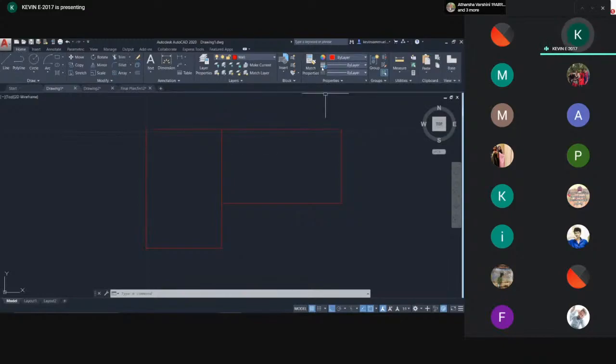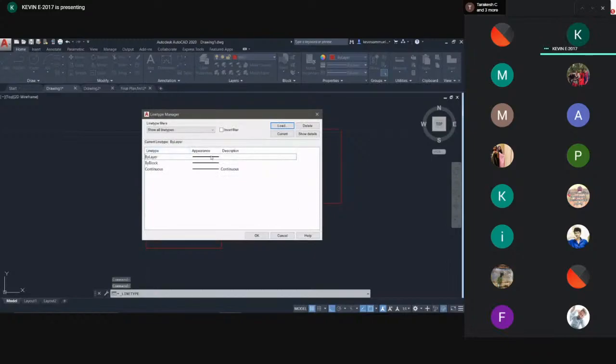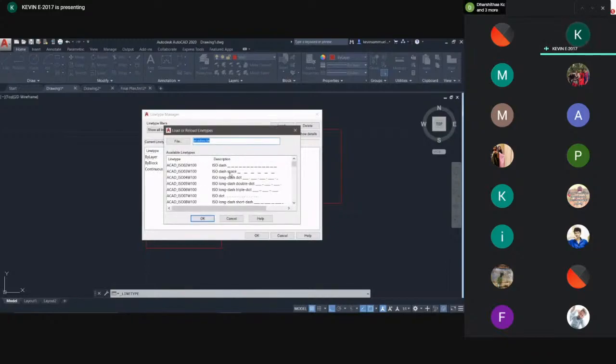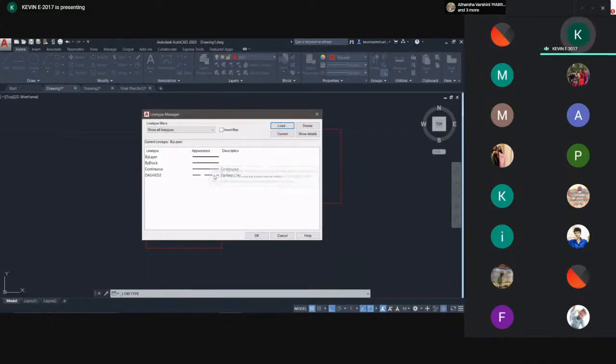you can see here there is an option line weight and an option line type. You can just click here. It is always saying by layer. If you want to change the line type, you can click here Other. These are usually used line types. If you want even more, you can go to Load, and there are immense line types you can use. So for now, I'll be using dashed lines, and I'm clicking this. This is the sample of the line, and I'm clicking it. Okay, so this line will automatically come here. So I'm clicking it. Okay.